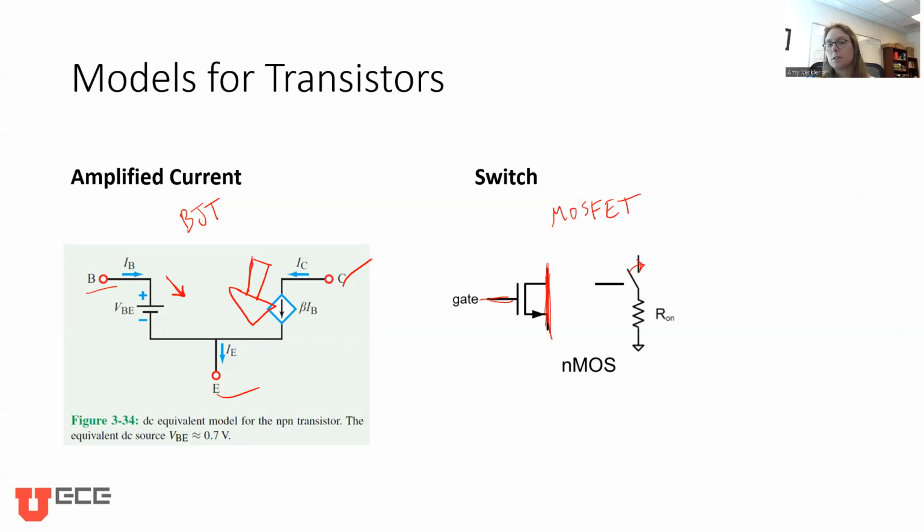So the switch flips, and there's a slight resistance inside of this transistor. And so by applying a voltage, we basically allowed the circuit on the other side connecting the drain and source to connect and create a complete circuit, and therefore we turn something on. And that's why it's called an electronically controlled switch, because I didn't have to physically flip the switch. Instead, I just applied a voltage at the gate.